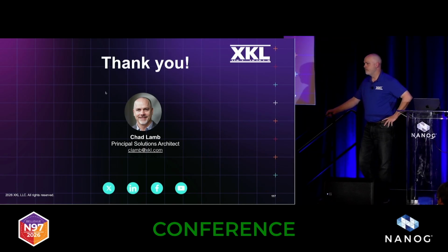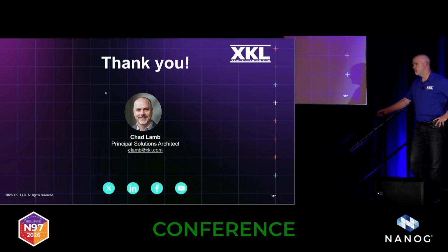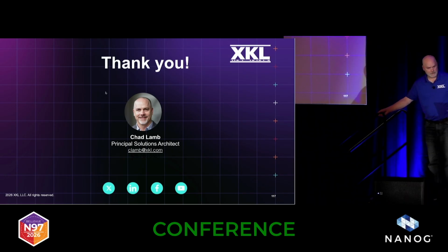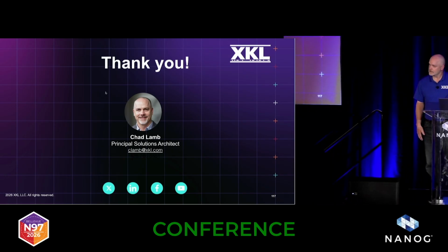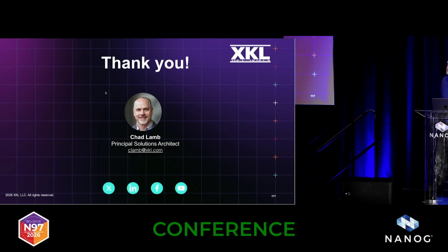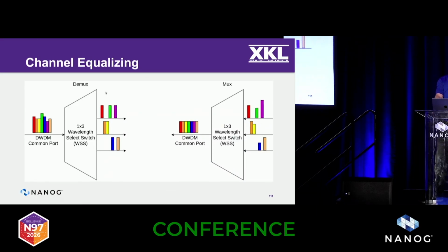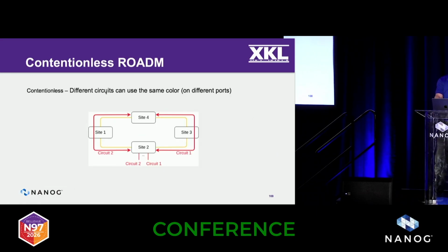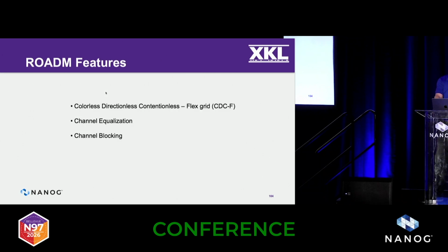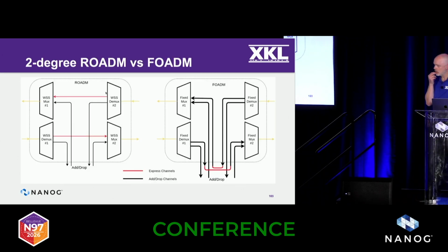I'm with Optic Networks. I had a question regarding the FOTM, the fixed grid, that you were talking about. If you were going to do basically not add drop at a location, you could just run a jumper between the two directions. Is that a feasible solution? I've been told to not do that, that you would need a device in between them to basically boost the signal. I guess it kind of depends on the distance, but.